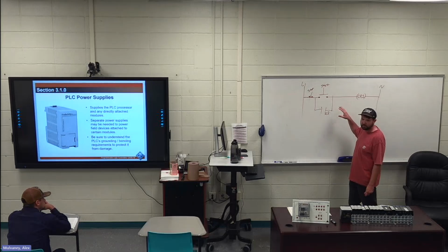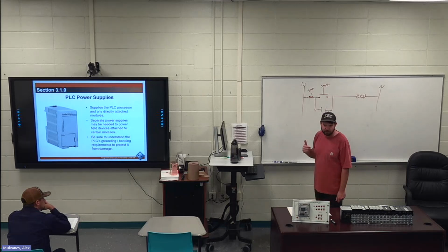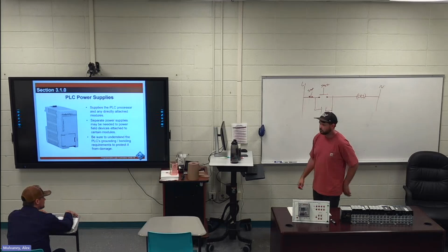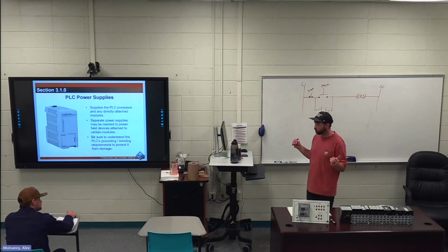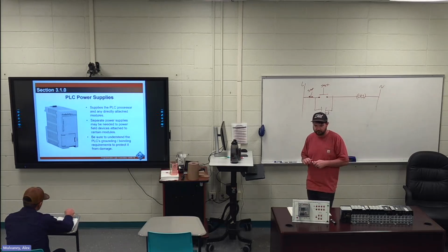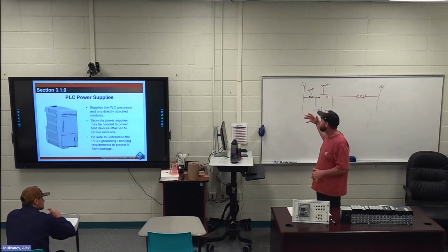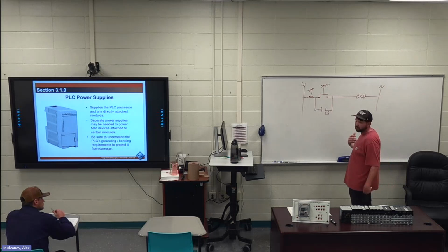Does that make sense? Volatile memory is temporary information that is not stored forever, right? The program is kept in non-volatile memory, and how the program is working is kept in volatile memory. A valve or a pump would be non-volatile, meaning it knows it's there, whether it's on or off would be volatile. Right, in the moment. However it is normally supposed to be is how it will be when the power comes back on, like turning it on for the first time. But how it is the moment power goes off, that's the volatile memory. It's still data that is communicated, still ones and zeros held in place while this is running. It's just wiped out when power shuts off.